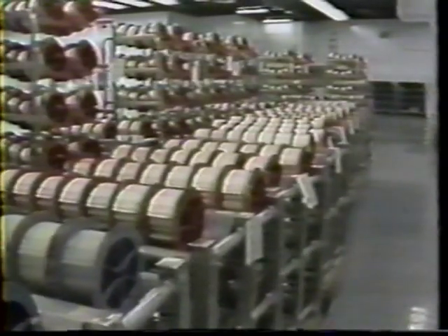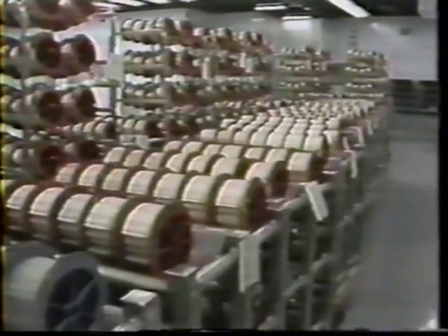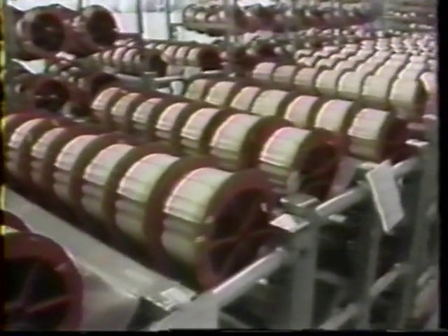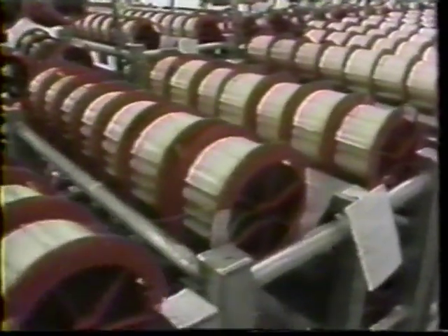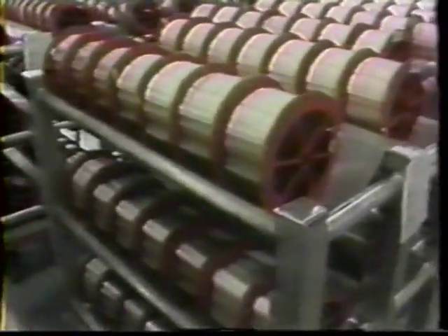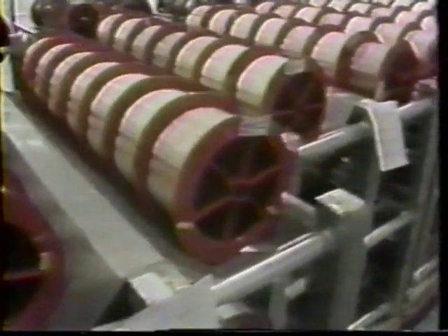Step 4 in the light guide manufacturing process is to assemble the light guide fibers into units, either ribbon or stranded units. Fiber is chosen to be of the quality desired or better, based upon its length and transmission characteristics.